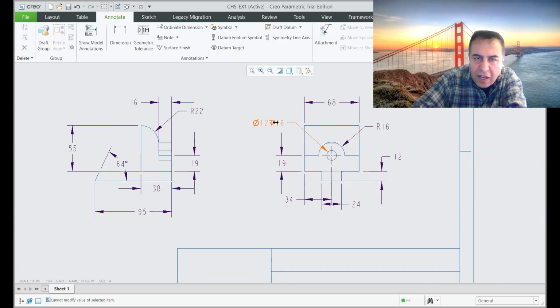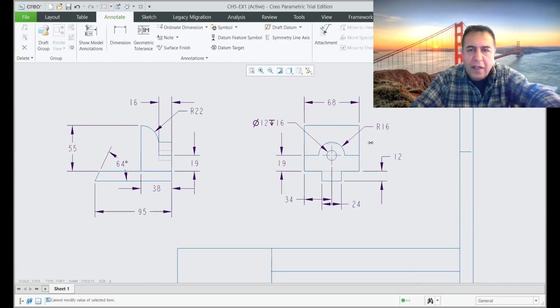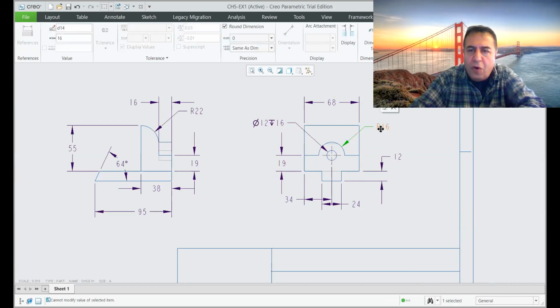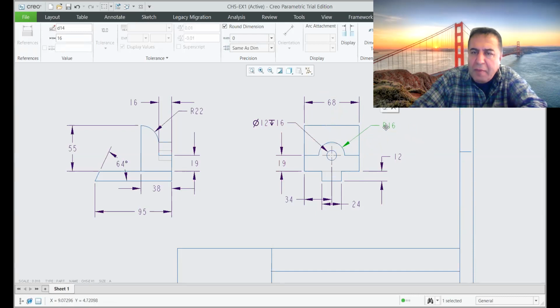This is a leader line. You don't want your leader line to be vertical or like that. That is incorrect. You don't want that to be horizontal. That's incorrect. You need to give an angle, approximate, eyeball it. It's about a 45-degree angle with respect to the horizontal line, okay?